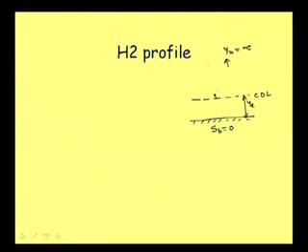So, zone 1 does not exist here. We cannot have anything beyond infinity, which should have been zone 1 beyond normal depth. The portion just above critical depth and below normal depth, because normal depth is at infinity, is zone 2.